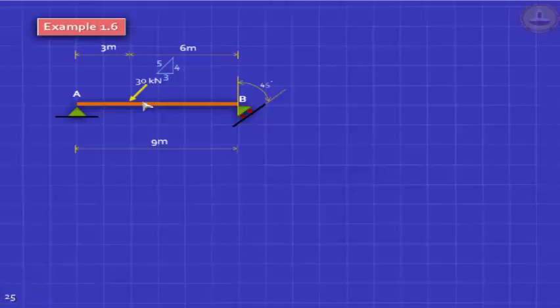Question is very simple. First of all, what are your reactions? If you stick to Cartesian coordinates, you have HA, VA. HA is horizontal at A, VA is vertical at A, and you have HB, VB. Here's the clue already leaked out to you. The one thing you know for sure is that because the roller is at 45°, they are not independent.